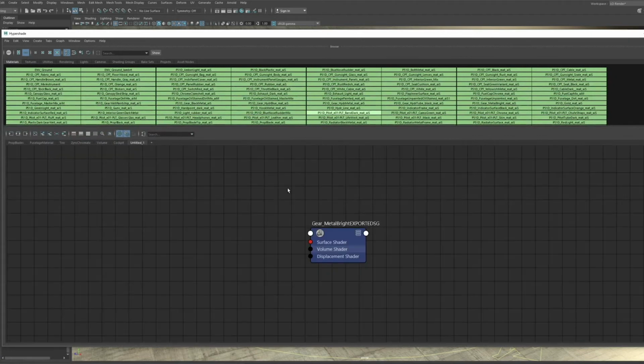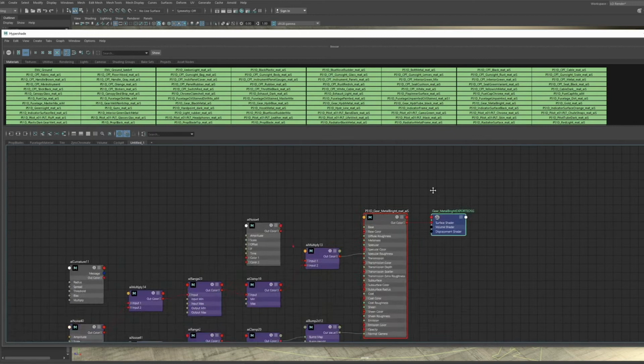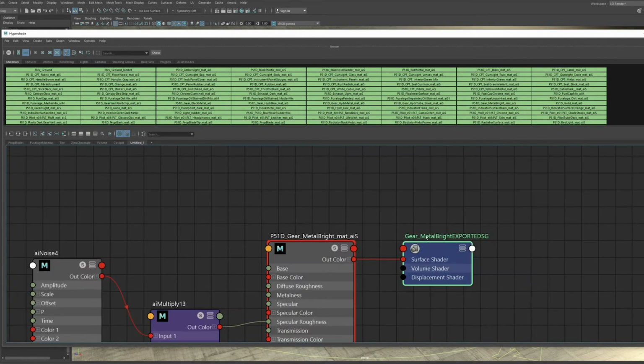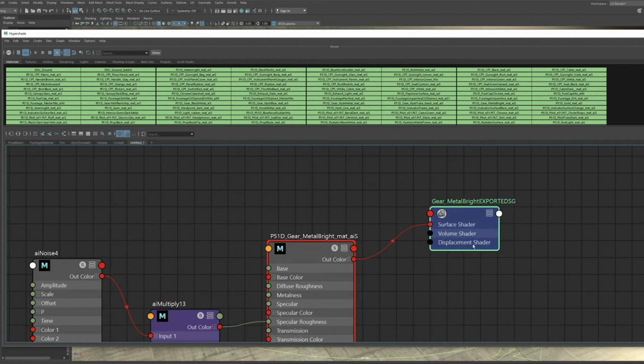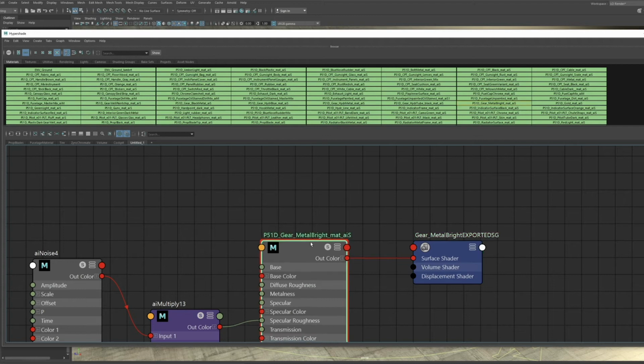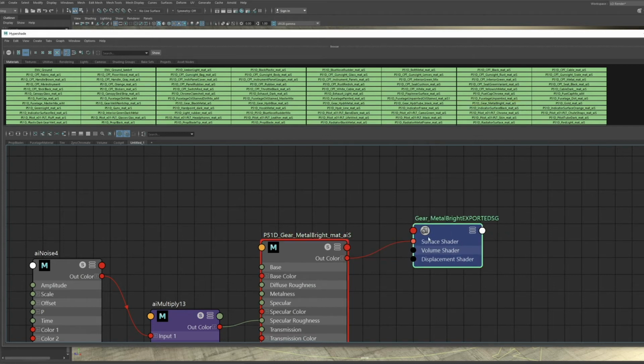Let me push that button, and you will have graphed that material. So the one thing here, the shading group, which is the thing that is actually assigning your shader to your object. It will usually have some name that it was assigned at the very beginning when you created the shader. So usually they are called something like AI standard surface 23.